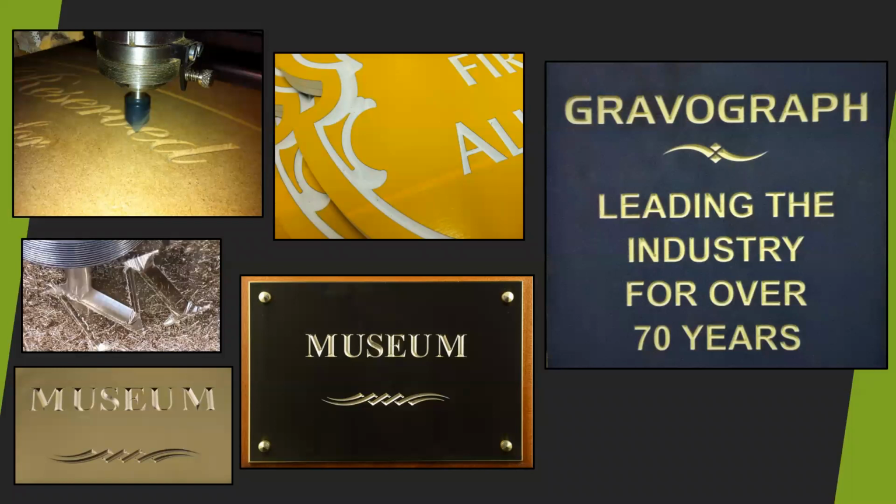In this session, we'll discuss utilizing the 2.5D toolpaths Intaglio and Prismatic as seen in some of the images. Essentially, these are V-carve toolpaths or relief toolpaths, depending on which toolpath we're discussing. So we can see that the cutter is varying the depth it is engaged into the material to control the width of the cut line.